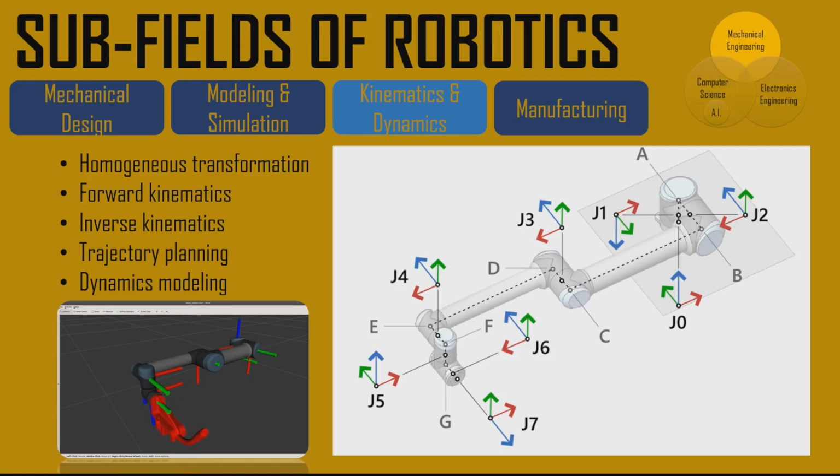And then comes the concept of forward kinematics and inverse kinematics. Forward kinematics is, simply put, when you know the individual joint angles of a particular robotic arm, and you want to find the position, the orientation, the velocity, the acceleration of the end effector. You do that by something called forward kinematics, which is basically nothing but simple mathematical, geometrical calculations that involve the use of matrices and linear algebra and stuff like that.